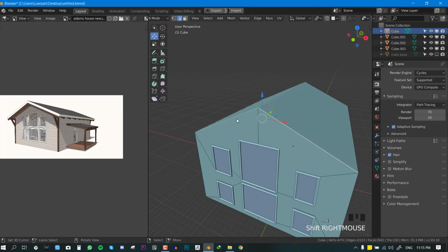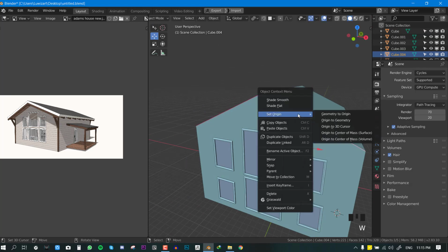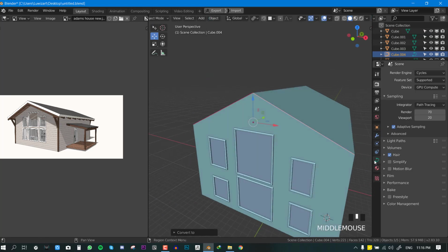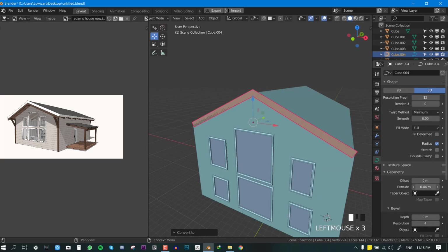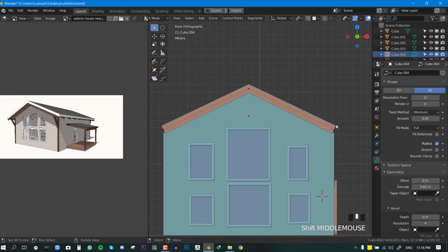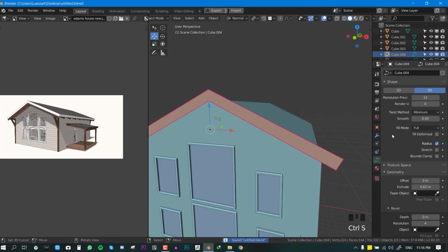So for the roof, we'll first start with the structure. So for that, we'll select two edges and we'll be going procedural with this. So selecting those two edges will convert it from mesh to curve. And now we'll go to the curve parameter and just extrude it to be flat like a wood. And this is just to give us more control over time, and we can tweak things along the way in case it's not looking so nice.